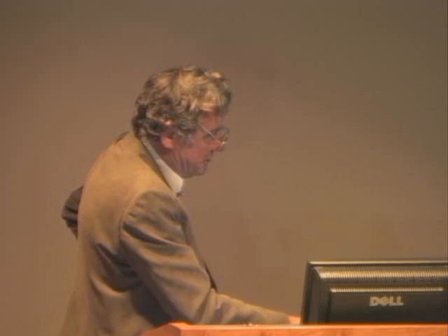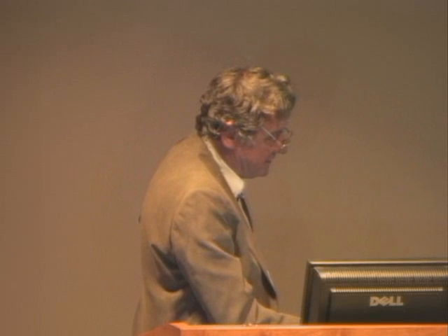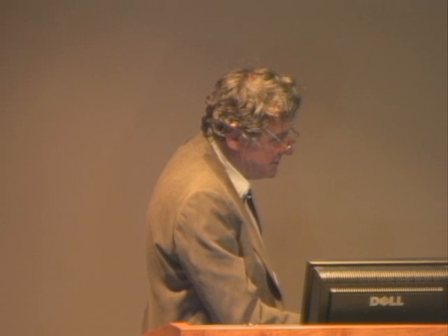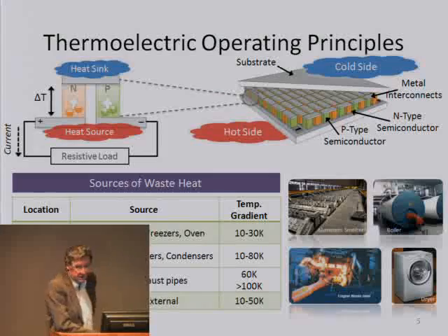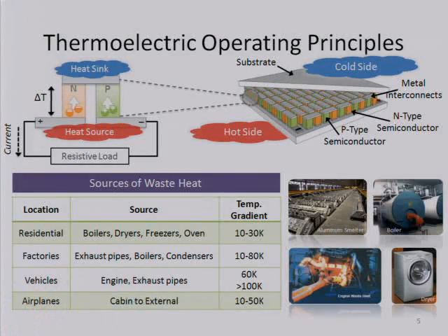Well, let me give you a little personal experience. So this is an aluminum plant here. The inside of these electrolytic cells here is at 960 degrees Celsius. And we have powered wireless devices by placing thermoelectric generators on the outside of these things, where temperatures are of the order of about 100, 150 degrees. Now, those are not our thermoelectric generators. They are commercially available ones. For this application, we're not interested in having things that are tiny, for example. So, yes, it's a consideration.